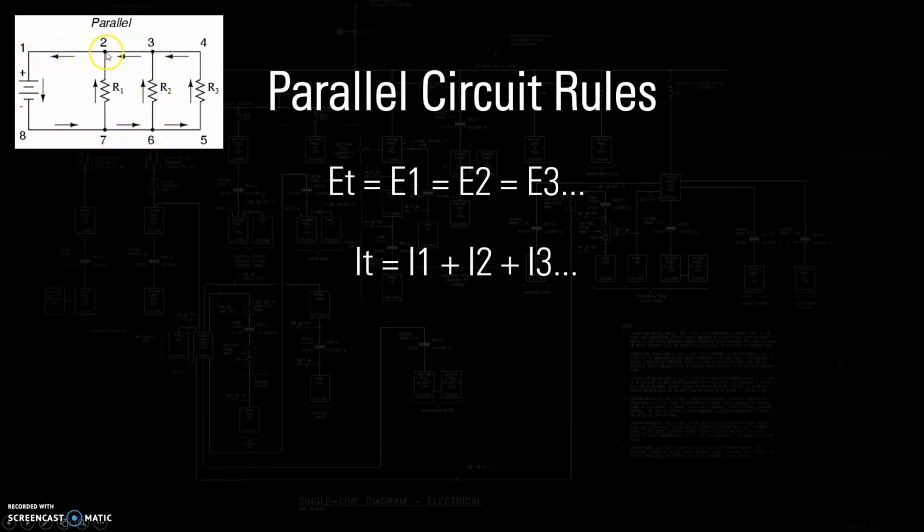You have to consider that on this portion of the circuit, we will have the added current of both of these loads, and we'll take that one step further. We have 1 more amp that flows this way. So on this portion of the circuit, we have 3 amps. On this portion, we have 3 amps. Only 1 goes up through here, so we lose 1. On this portion, we now have 2 amps, because we're still carrying the loads from these two.